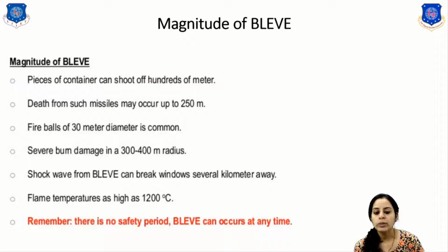The shockwave from the BLEVE can break windows several kilometers away. Flame temperatures are as high as 1200 degrees Celsius. And remember, there is no safety period and a BLEVE can occur at any time. Okay, so this is a BLEVE.